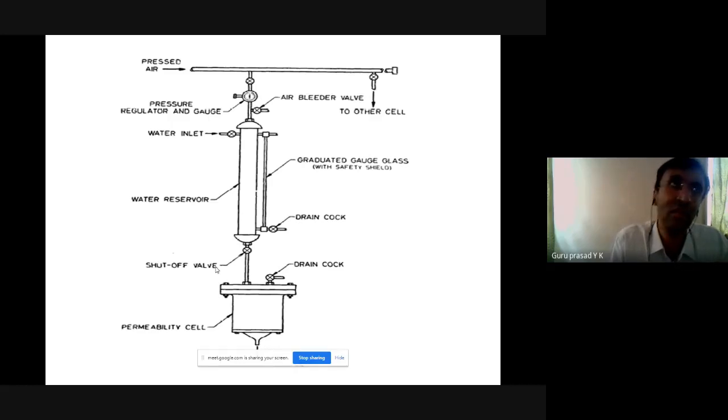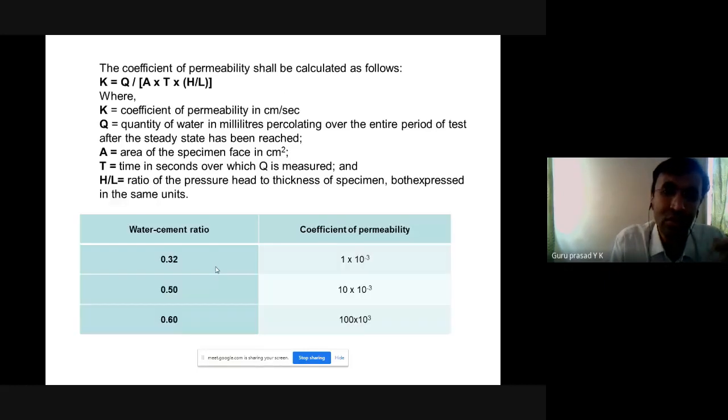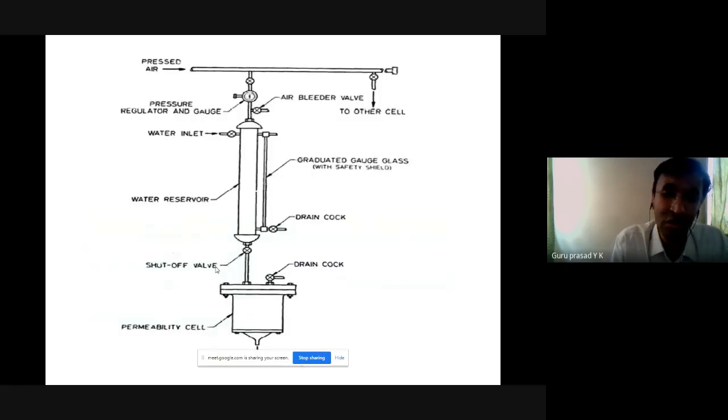See, in our houses also, when it rains, only if the concrete slab is cracked will the water come in immediately. But in certain cases, after a certain amount of time following the rain, you'll start seeing damp patches in your slabs, right? It does not happen immediately. That is permeability, basically the water passing through the voids and micro cracks which have formed in the concrete.